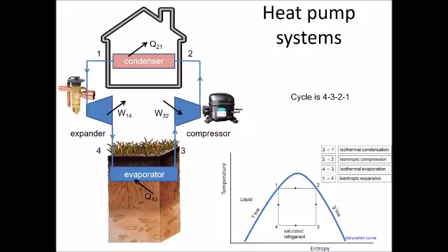So actually, in this case, the focus of my attention, where I'm going to set my thermodynamic solution up, is from the perspective of the condenser, not the evaporator. It was the evaporator for the fridge or the freezer, but for the heat pump system to provide heat, it's the condenser that is the focus of the calculations. That's where the heat is going. That's what I'm interested in. The work process is still the same, but the heat is going out to the condenser, and that's what I want to do my calculations based on. All right, so let's go and do that.